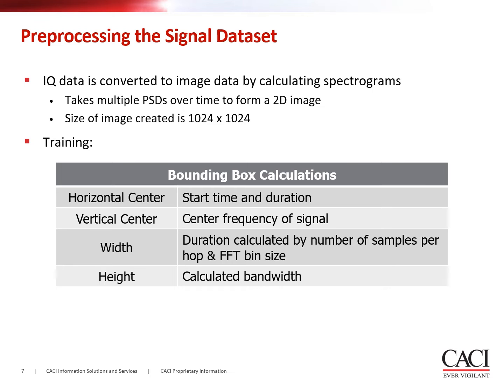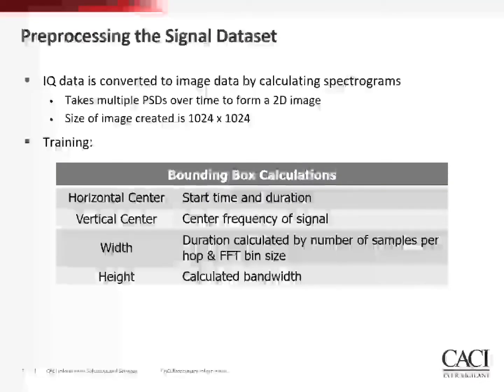In some experiments, additional interferer bursts were randomly added throughout all 4 images, including in band within the signal of interest. The size of the stitched image containing the signal of interest and 3 random interferers was 2048 by 2048, which was automatically scaled down by YOLO to 1024 by 1024.